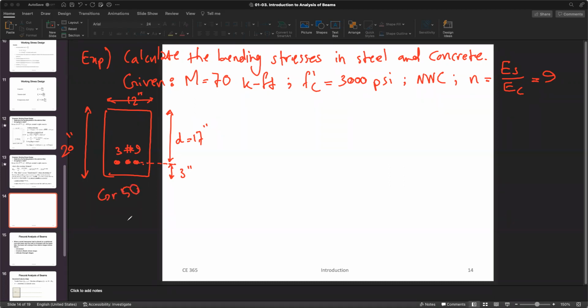All right. So talking about the reinforcement, this number 9, I'm going to show you maybe. There is a reinforcement chart for American reinforcement bars that goes from number 3 all the way to number, if I'm not wrong, 18 or something. It is a standard reinforcement pattern where the size, cross section, and diameter are often given based on the number associated to that. So here in this problem, we are using number 9.